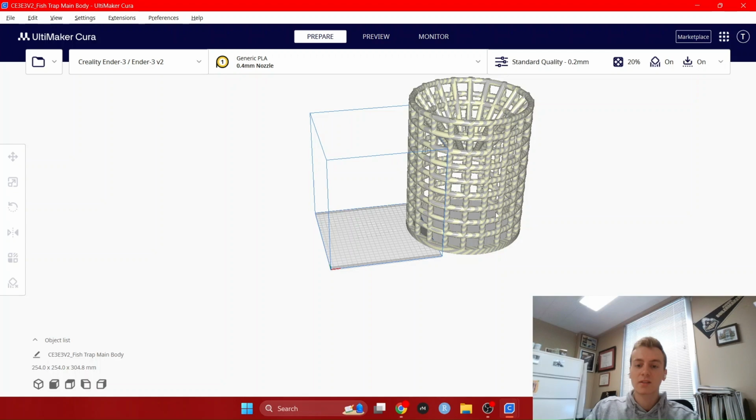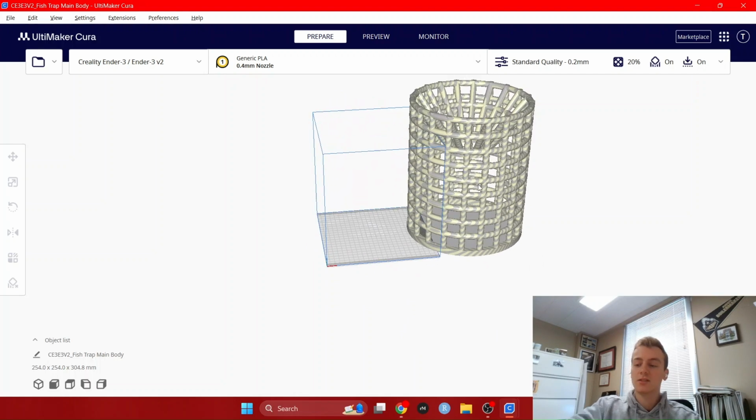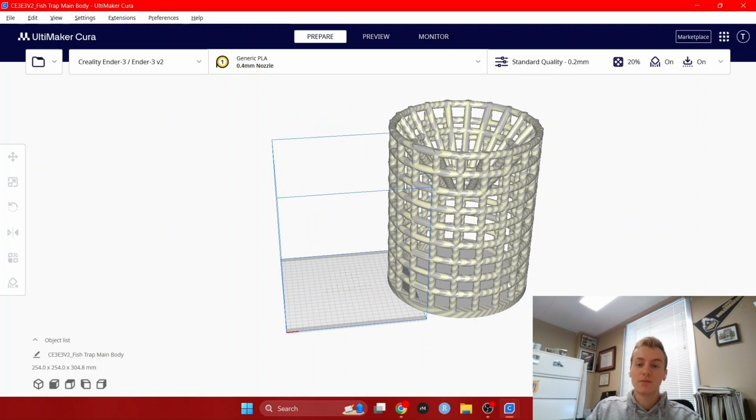So you see it's pretty big because I made it a foot tall, which for 3D printing is a lot of time. I was looking at it yesterday when I printed these out. This with supports would take a little over 5 days, so that's a lot. And it would take like 600 grams, so more than half a kilogram of filament. So if you really wanted to print it that big, you'd have to make sure it fits inside your printer size. But that's doable. It's a little crazy, a little bonkers, but very doable. Bonkers is sometimes fun.